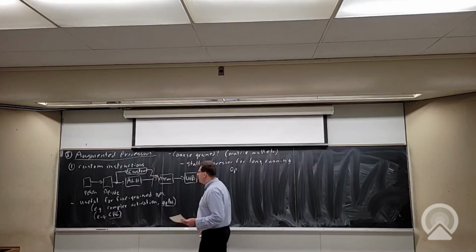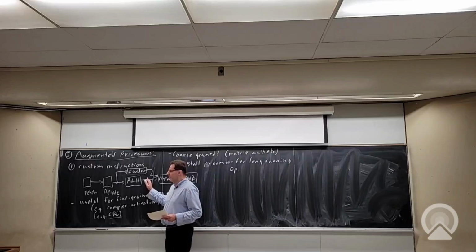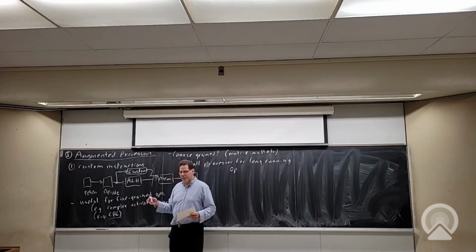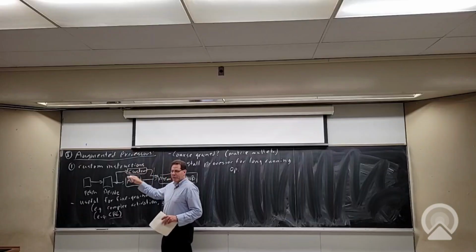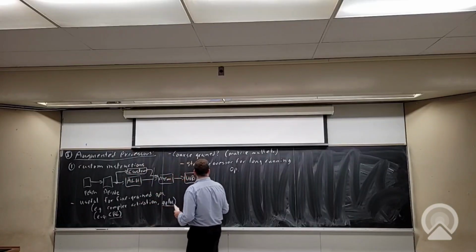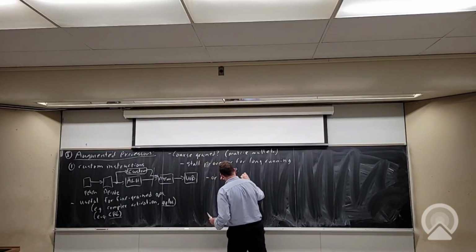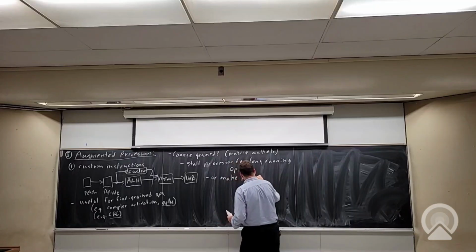So I think Nios actually stalls, right? In other words, you can send it an instruction and it will basically stall the pipeline. Now you could also say, I'm not going to stall, and you'll just negotiate to get the memory when it comes back and tell the programmer, make sure that you're not depending on this result. So I guess you're right. Or make the processor a bit more complicated. And maybe Altera's done that with Nios now.